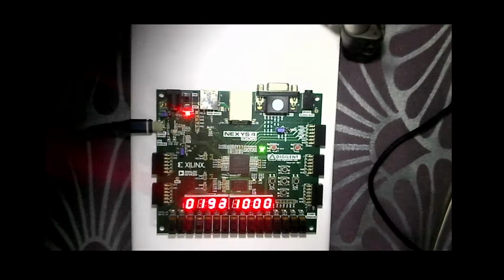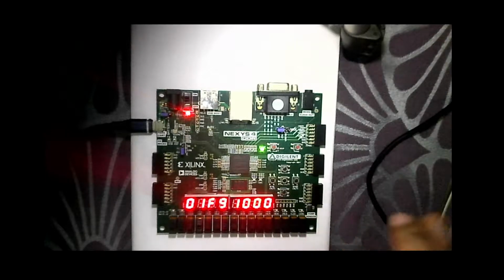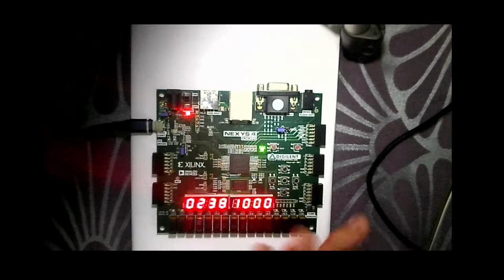So this is a hex counter which is up counting from 000 to a number which you specify using this 16-bit switch here, right? Whatever you put in here, the counter will count to only that and then reset back to 00. In most microprocessors you will have these counters. You feed in a count and it counts to that and resets it. So this is one of the components which can go into a microprocessor or microcontroller.